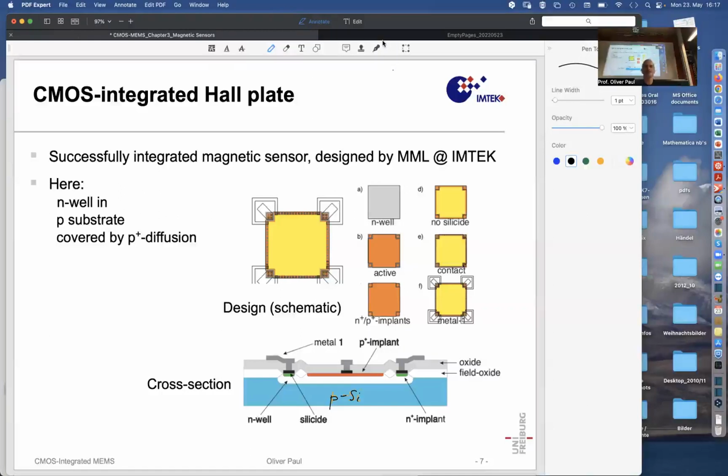So this depth here, as I said, is maybe, let's say, 3 to 4 microns. Much more is difficult to fabricate, but that is the depth that is used in so-called high voltage technology, where tens of volts need to be dealt with in microelectronic circuitry. So it's not an exotic thing. It's just that not all CMOS technologies have those deep wells.